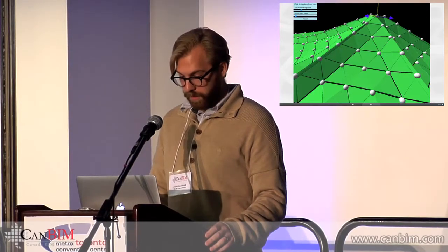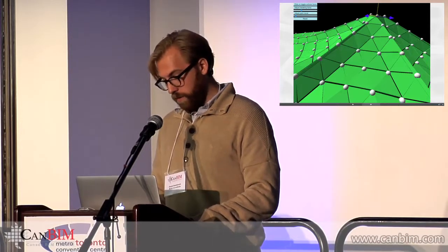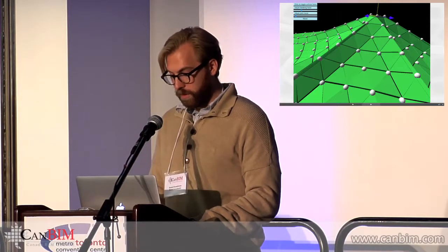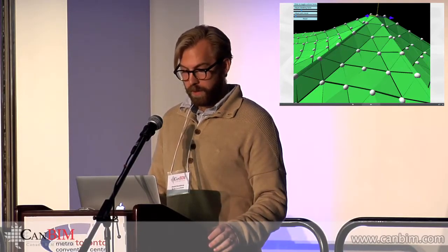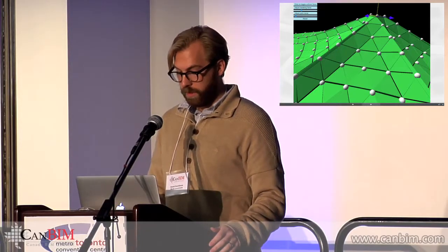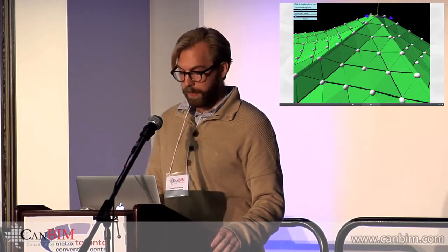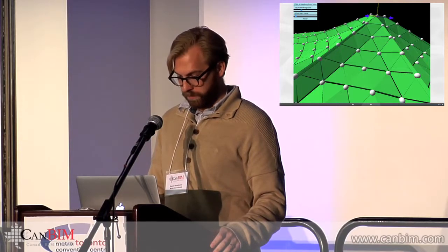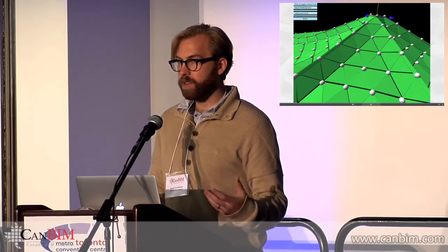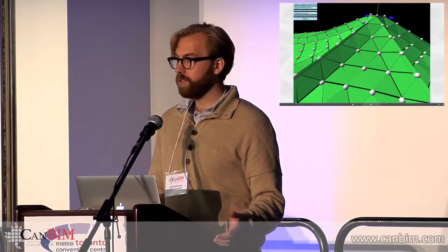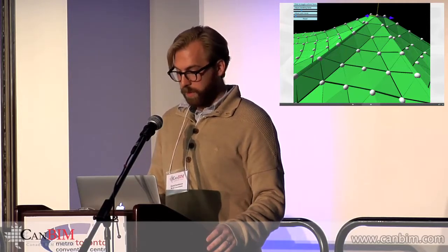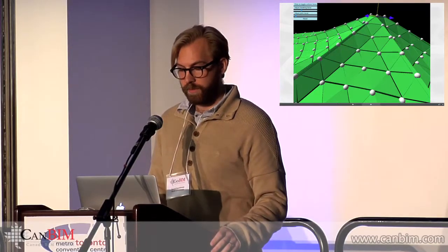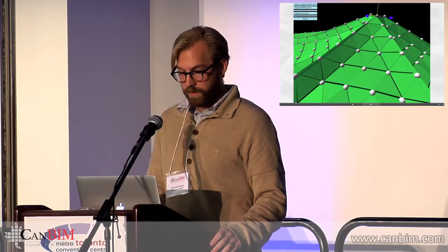As one more example, to get something a little bit smoother, you can keep the corners of this structure locked in position, but they're able to rotate. And then we can apply uniform upwards force on this and see how this evolves into a dome-like structure. Already the behavior of these panels is very unintuitive. I don't think anyone could have sat down and drawn this structure. So right there, you have something that's significantly curved, leveraging the play between these panels. You can also, if the amount of tolerance between the panels is too large, adjust it and go from there.